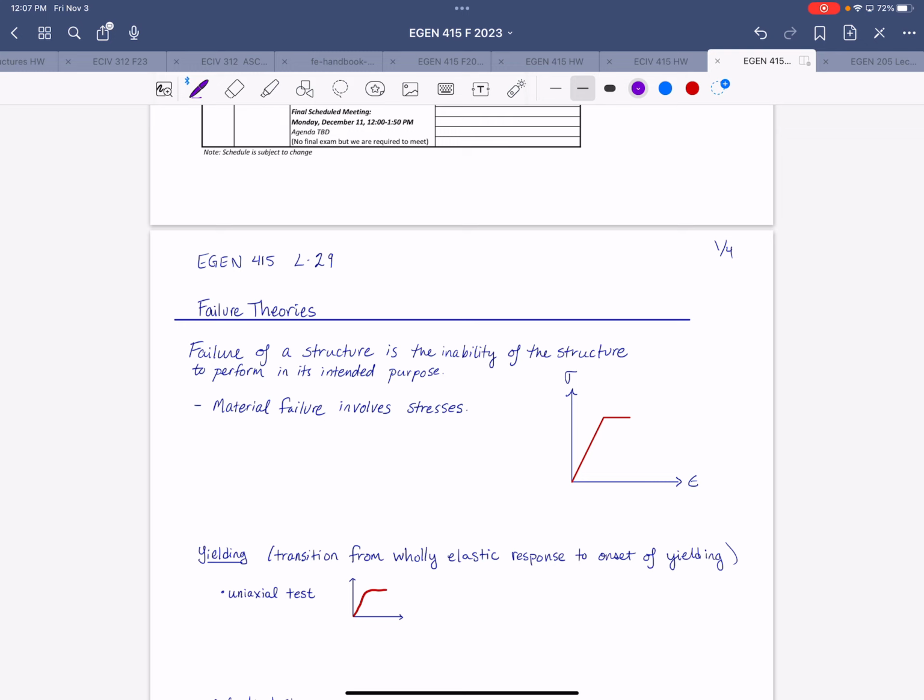Okay, can you repeat your question? Well, basically, because you add the dummy load, this is an indeterminate beam, so you cannot determine, using statics, the additional reactions based on the additional load. So would you have to go back through and do Castigliano's once again, setting the deflection at B equal to 0, and then solving for the dummy load?